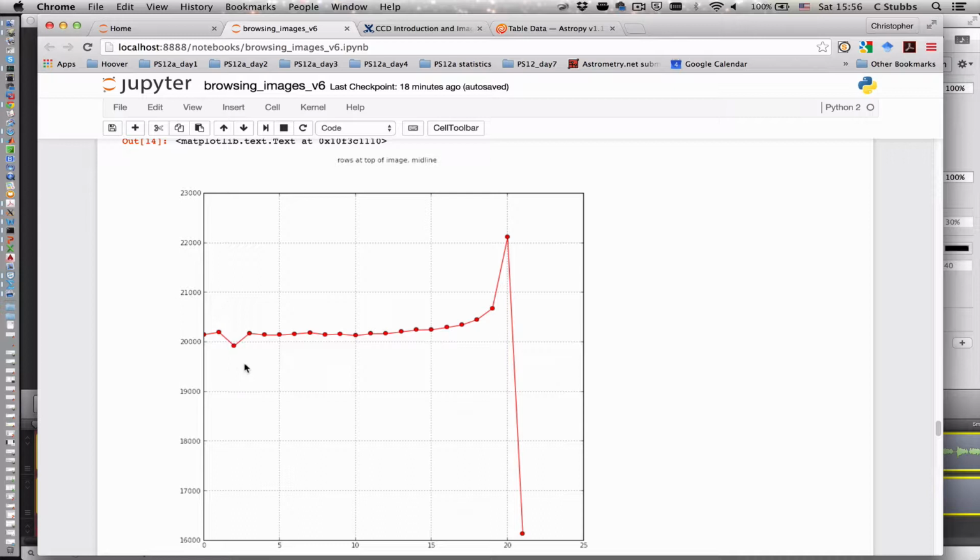This excursion of diminished flux about 15 rows or so below the midline, we understand comes about because of a mask anomaly that is intrinsic to every single one of the amplifiers in these chips. This can be flat fielded out and is not actually a substantial problem to us. So this is the first example of us encountering something that we can now explore quantitatively that we describe qualitatively as one of the features that afflict LSST CCDs.